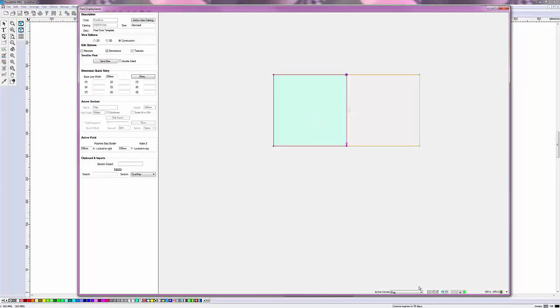Now, if I click on this icon down here, which is undo, or else I type Control Z, then that undoes what I just did. The first way I can repeat the particular size section is to put a number in one of these quick slots. Now if I say right click, line, and then I press 1 and hold it down, and then left click, then I get a section of height 200 millimeters.